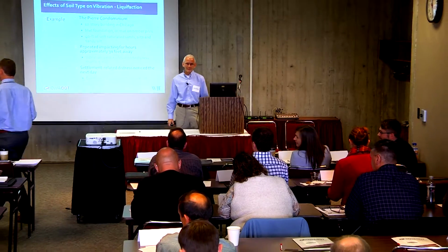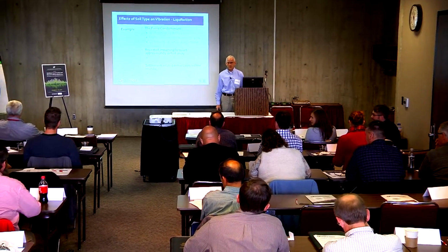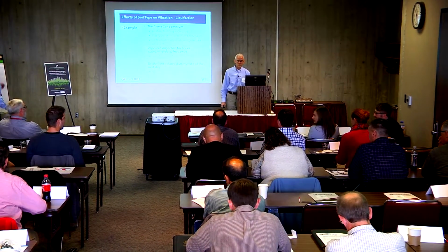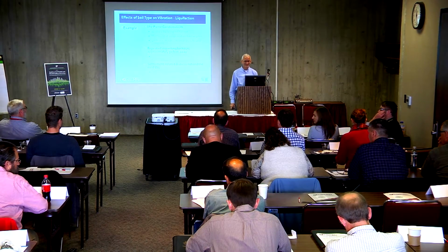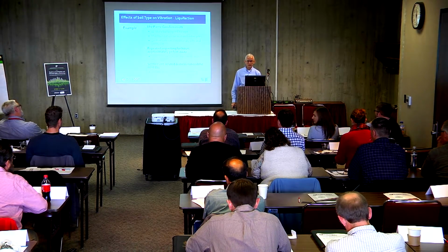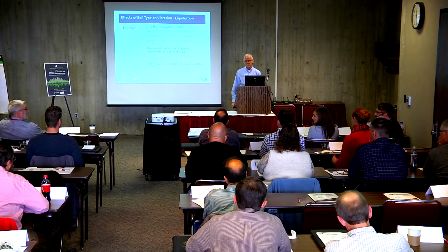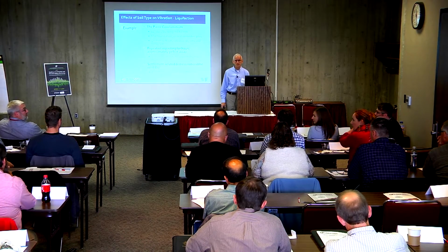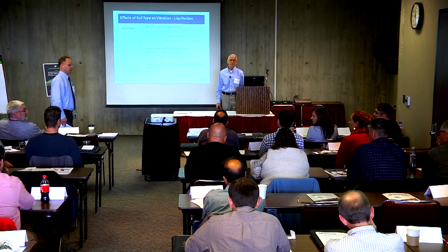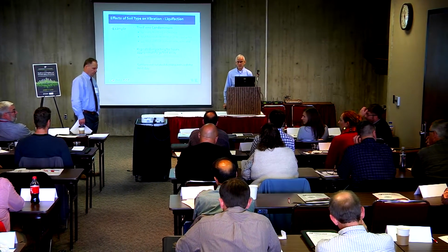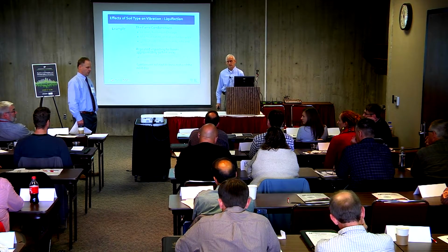Is there any time that you might want, if you have liquefiable soils, to find the right amplitude and the right frequency to make sure that it does liquefy, as a benefit to what you're doing? You're not trying to cause damage anywhere, but you're trying to get the caissons in the ground. Oh, yeah, and you find the right way to do it to liquefy it so the caissons go in easy.